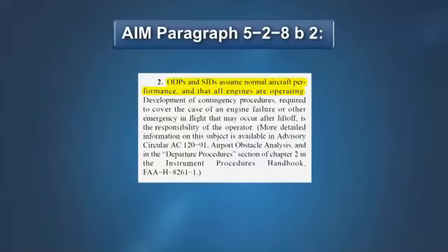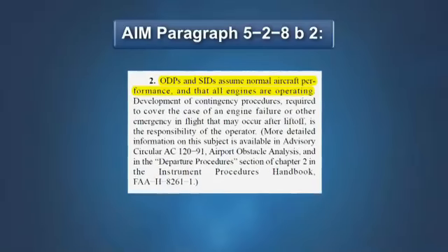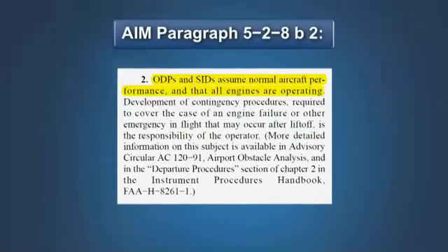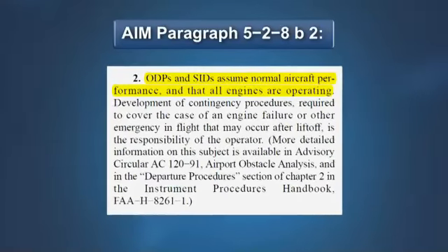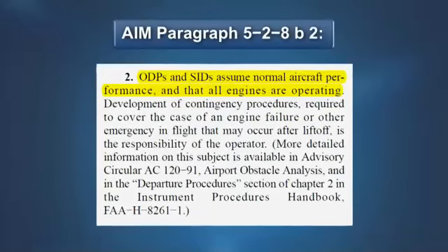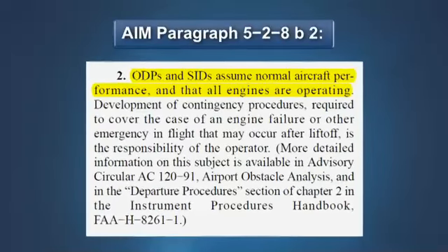All IFR departure procedures are based on normal airplane operation and assume that all engines are operating. Compliance with the climb gradient published on a SID or ODP is based on the normal all engines operating climb performance of the airplane. There is no requirement to demonstrate compliance with a SID or ODP based on one-engine-inoperative performance.